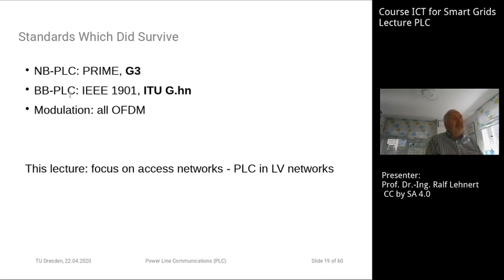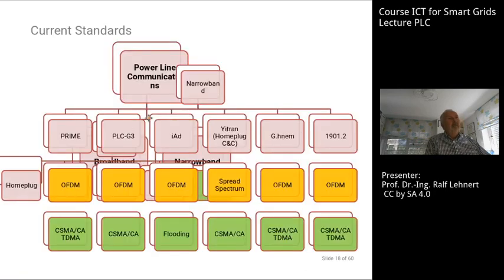And in broadband PLC, we did have standardization. The first standard was IEEE 1901, and it is now superseded and extended by the ITU G.hn standard. And all modern systems now are running OFDM. One of the earlier systems here, for instance, the Yitran implementation, was running with spread spectrum techniques.